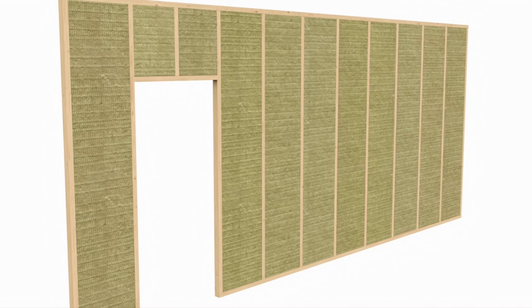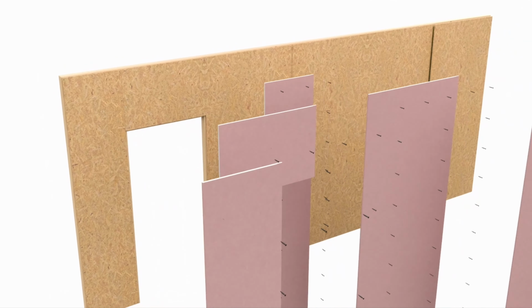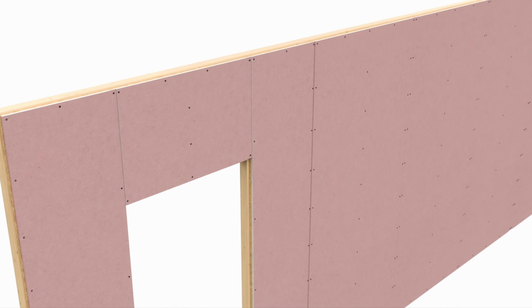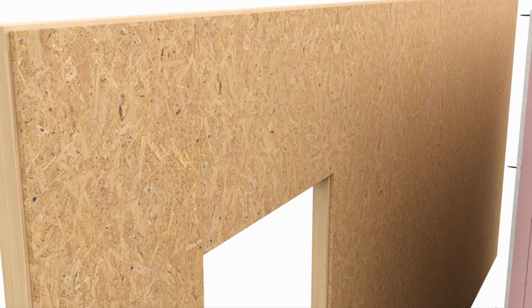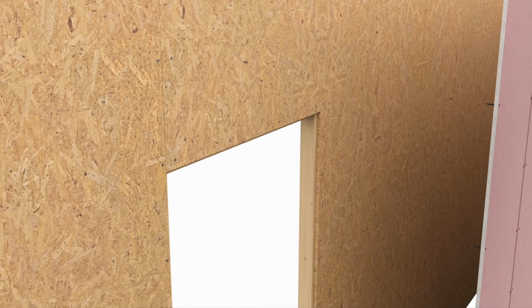in the wall. In the case of a 2-layer board covering, the bottom board layer can be wood-based, for example OSB board. The fastening of the bottom board layer must be made according to the type of material, as well as the assembly solution of a particular project. It is important to pay attention to the places of the opening fillings, where later there may be a need to install a corner strip. In such places, it may be necessary to leave the step of fasteners larger.